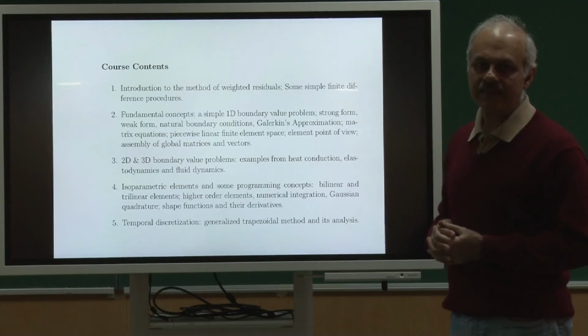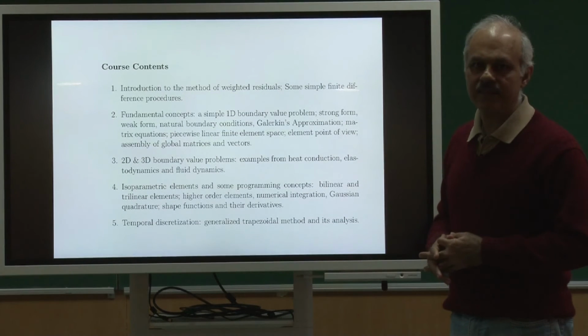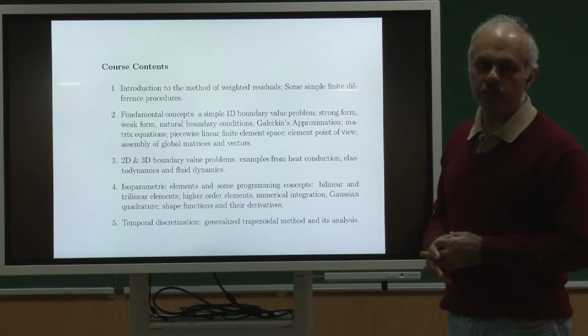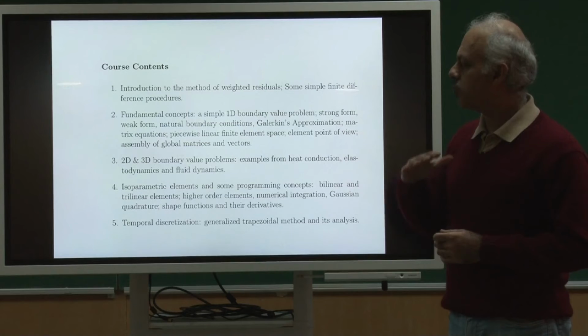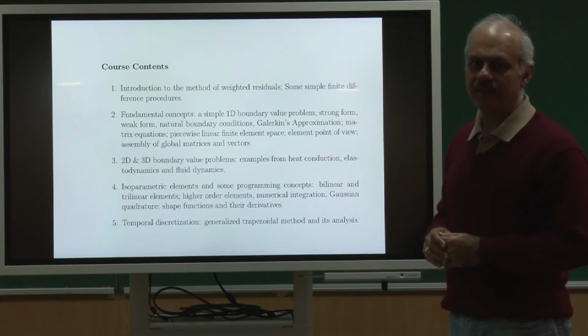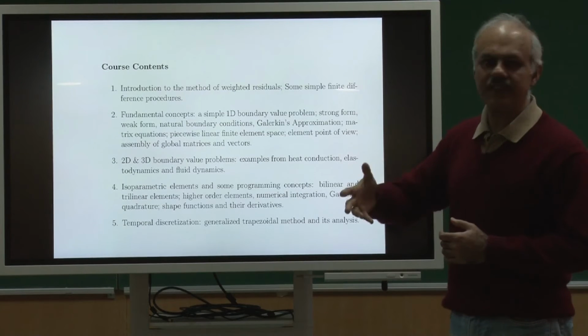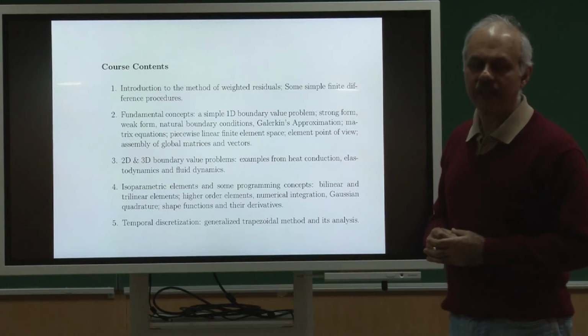Just to give you an idea, if I had to model, let us say, flow around an airplane, then even to model the surface of an airplane is a big challenge, okay, because a surface of an airplane could be extremely complex, and to be able to put grid points on the surface and then join them via some elements is not so trivial. In fact, the modeled surface that you may get could be a little bit different than the actual surface of an airplane.